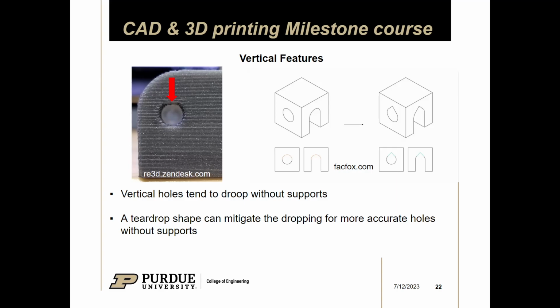What if for some reason you need it to be a perfect circle? Then what do you do? If you need the hole to be a perfect circle, then... Supports inside the hole? Yeah, you could use supports. That works too. Honestly, I've found that most of the time you actually don't need a perfect circle. I've made stuff for bolt holes and threaded inserts. I just made the teardrop shape and it worked just like a normal hole.